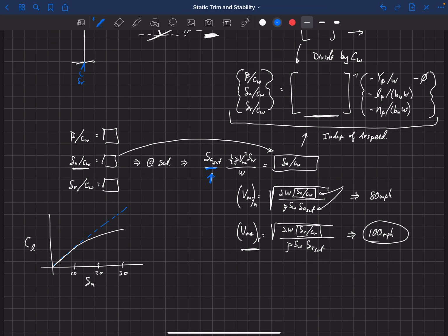If geometrically we can go out to 30 degrees, that's the maximum rolling moment we could get, but with this analysis we might say our saturation angle is actually 20 degrees, equivalent to 20 degrees of linear deflection. As long as you know the mapping of what the geometric deflection maps back to as some equivalent linear deflection, you can still use this analysis to compute the minimum control airspeed.